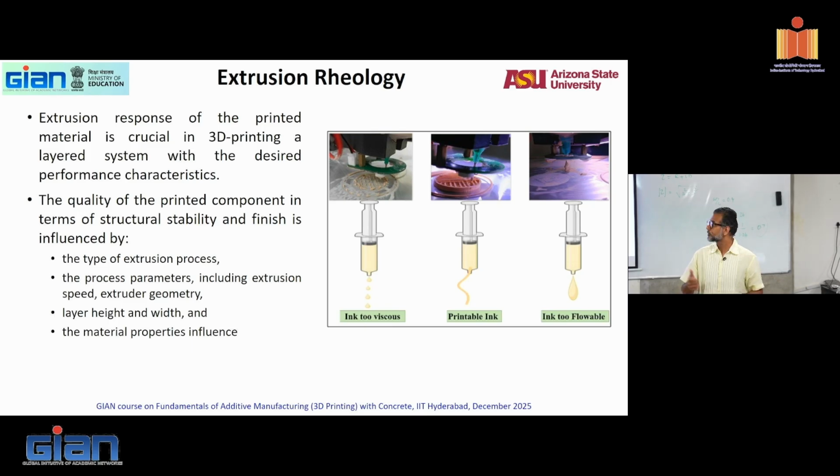We'll do that tomorrow. And then with oscillatory rheology, you know that you're applying a small sinusoidal amplitude, and therefore the output stress lags the input strain by a certain angle, which puts the whole thing in the complex mode. Therefore, your viscoelastic parameters are complex numbers, and you have to find the magnitude of a complex number.